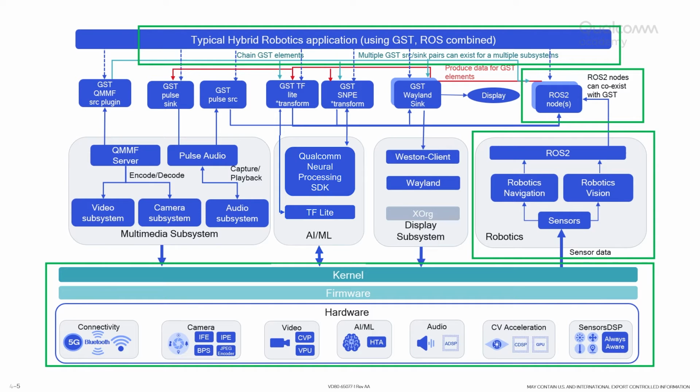And then once you have the ROS node data of the IMU sensors, once you have the camera data, you can integrate all of these different aspects within your robotics application using GStreamer plugins, right? You can daisy chain output and input from one particular element to the next element, and you can feed it to the ROS node. You can take output from the ROS node, feed it to your application based on what your use cases are. So let's get into it.